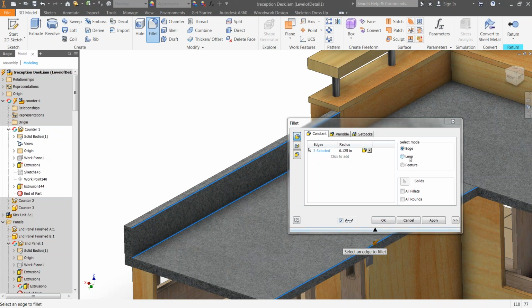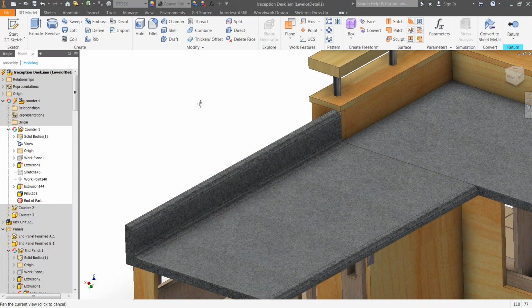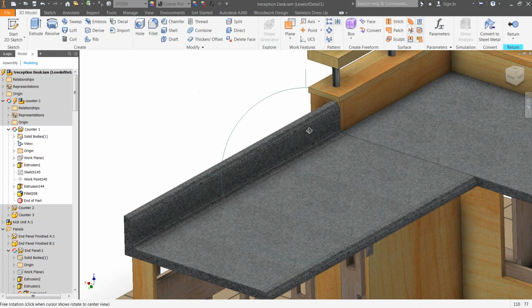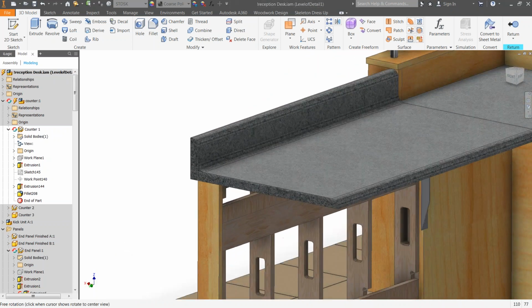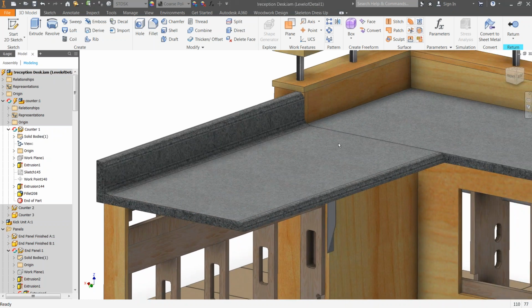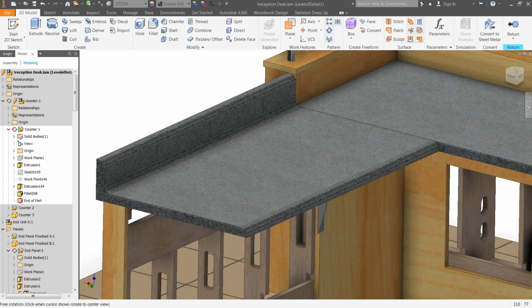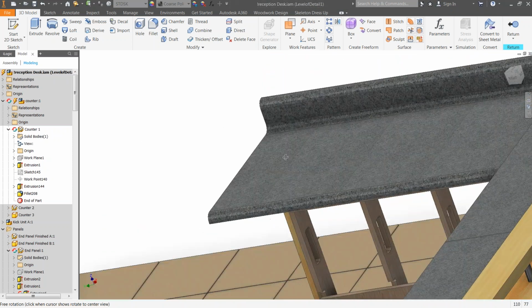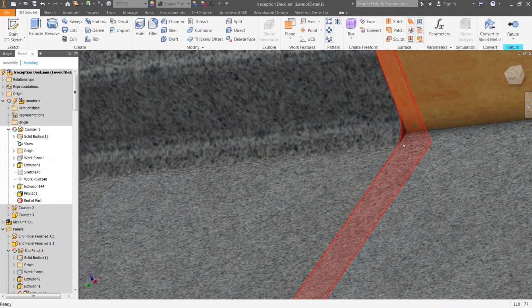But they also said post-form it, so I'm going to just fillet the outside, the inside, and the outside of this. And I'm going to say that this is, say, a 1-inch radius, and I pick OK. So this is what he asked you to do, and it's horrible. Okay, it truly is horrible. But you're showing him that's what he asked for, that's what he's getting, okay? Now in this world here, what's interesting about this is even if he likes this and he says go ahead and do it, then you, by rotating this model around and looking at this inside corner, you say, well wait, what are you going to do about that?